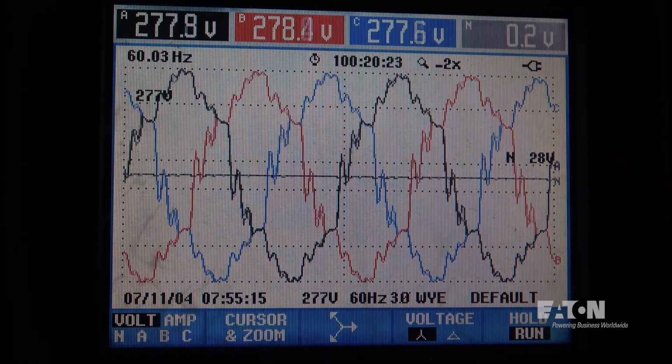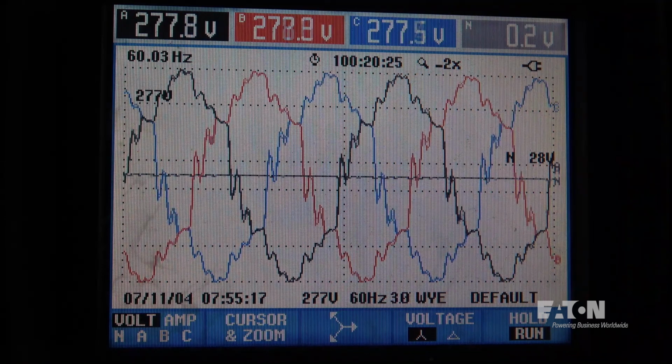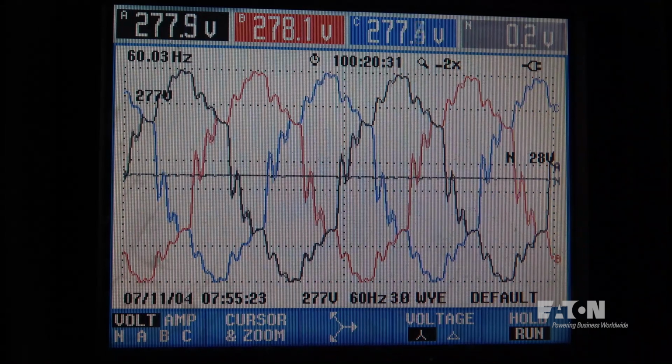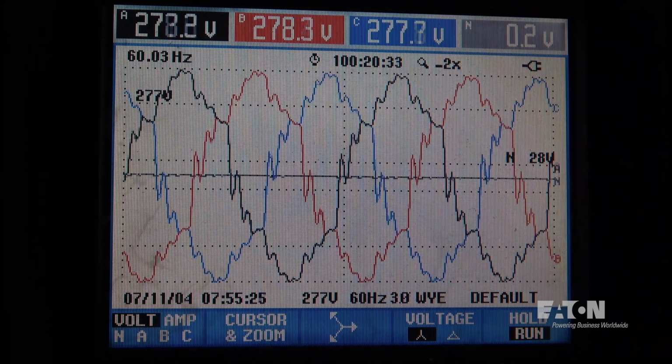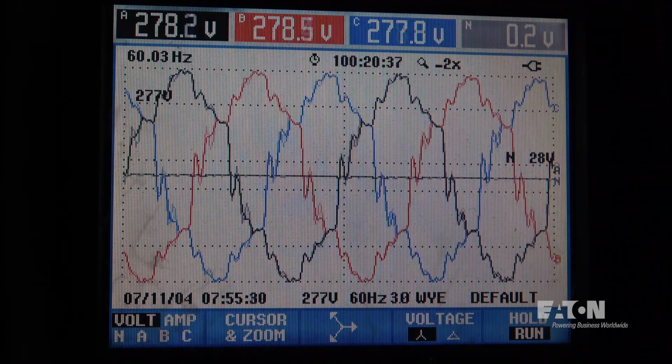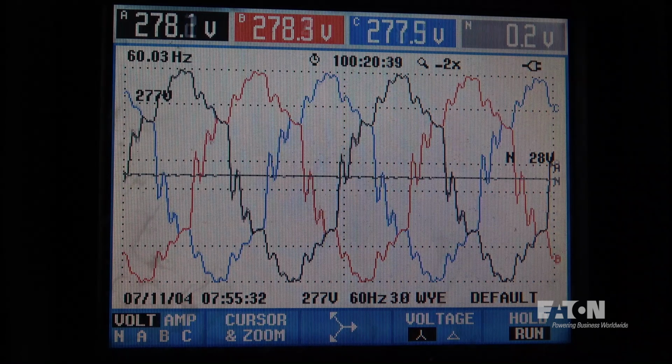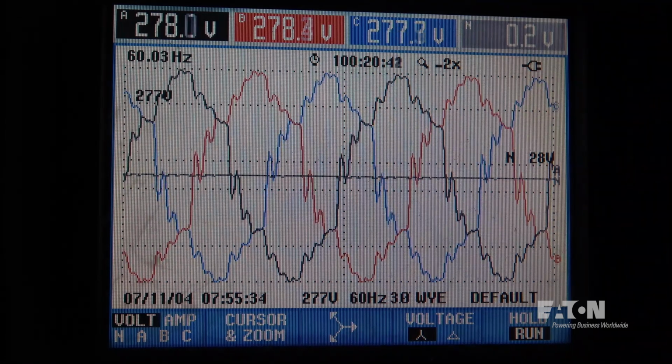And if we have that happen, some equipment that's synchronizing based on normal 16.67 milliseconds per cycle, 2 times the voltage crosses zero, that's not normal in this case because what's happening is we're getting a lot more crossings. So we turn that off.